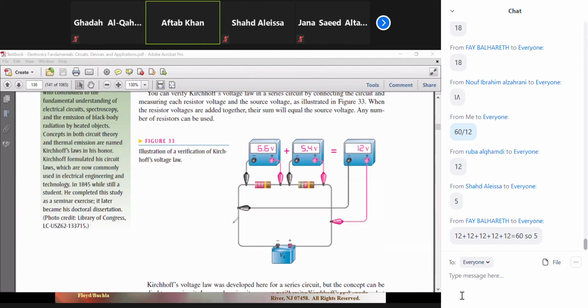If we want to measure current, we need to break somewhere. Yani, let's suppose we break this wire from here, cut it from here. When it is cut, now I can connect the ammeter so that it becomes a series connection. Then the current will flow this way, pass through it, and it will measure it. So we cannot connect the ammeter in parallel. You will learn this one in the lab.